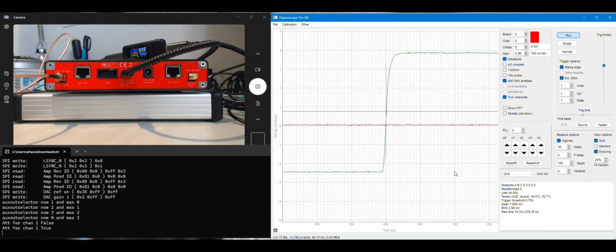And yeah, so that's the basic functionality. I guess one other thing I'll mention is if we look at channel 1 again, and maybe we'll go back to triggering on it instead of the external trigger so that it's not jumping around so much, you can see we're actually measuring some things here. We're measuring the mean of the signal, the RMS, and also the rise time of that green signal.